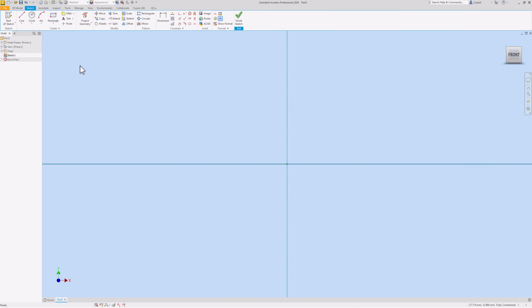And what I'm going to do is try to sketch what the front view of this ET-looking head thing is. I have no idea what this is. I'm just going to go to Line. I'm going to draw a line, just random anywhere, and over to the right by 10. Right click, hit OK. I want to move this line so the middle of this line is right in the middle of our origin.